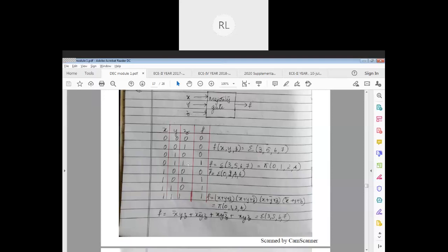Similar case here, but here the case reverses. I have just 1 zero and 2 ones. So a majority of high bits gives a high output. Majority of ones, so I take my output as 1. Similarly here, zeros are more than ones, so 0, 1, 1, 1. Is this concept clear? How we are getting the truth table?